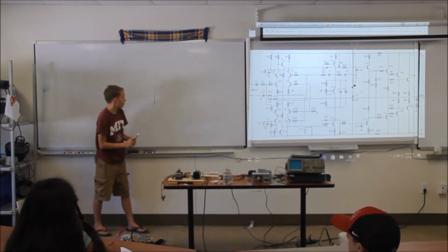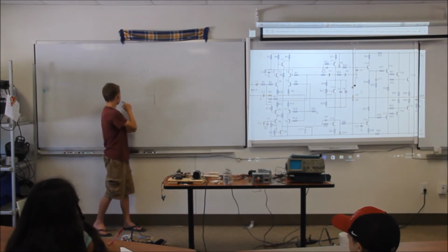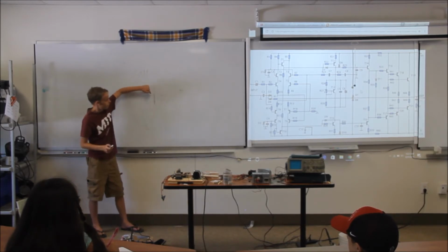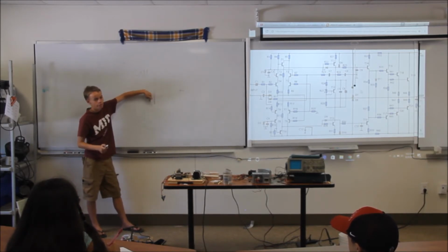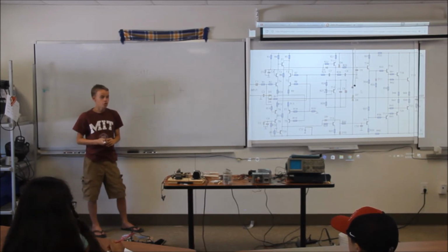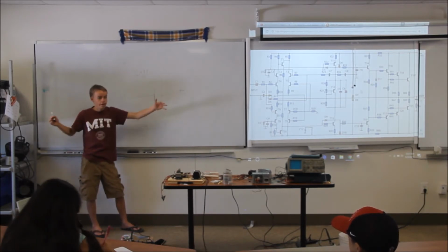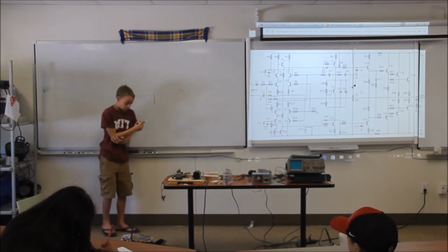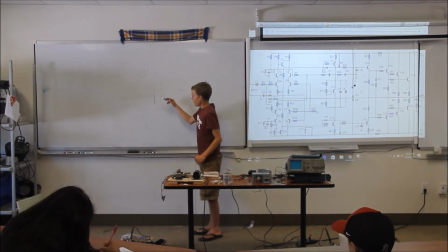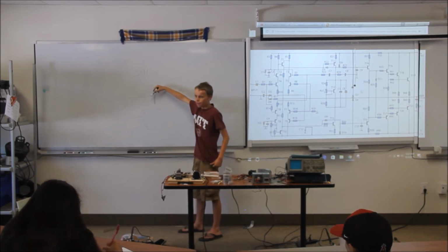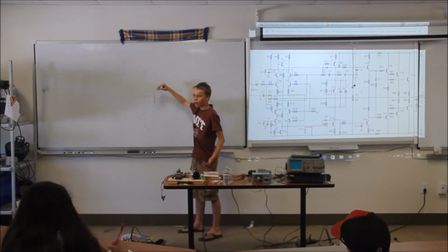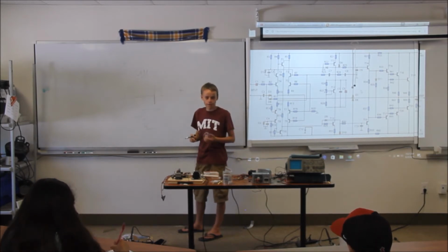With AC current, since the plates are constantly switching from positive to negative and negative to positive, the current is always going to be allowed to flow through the capacitor. So if you have a bigger capacitor, then it's going to take longer to charge. If the current flows through and it's not fully charged and then it switches direction and tries to flow the other way, that means not as much current is going to be able to flow.